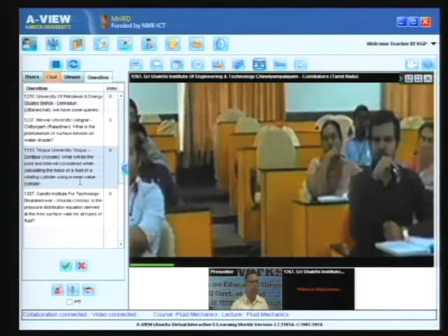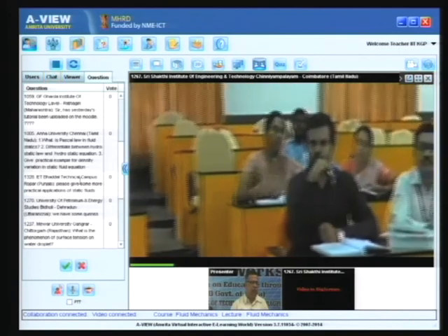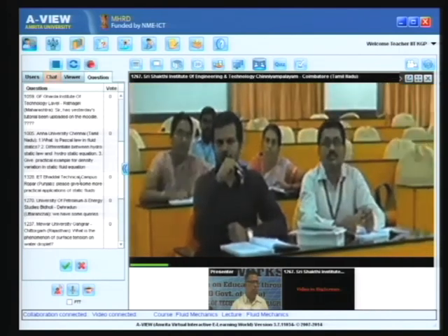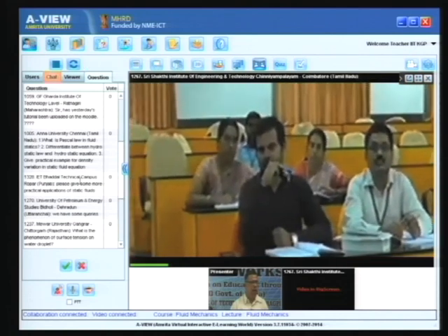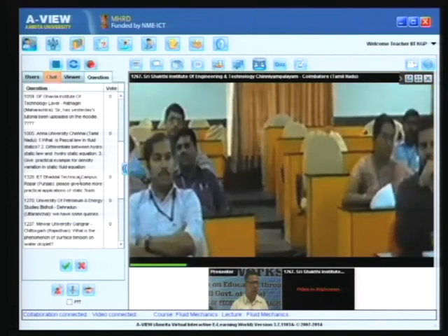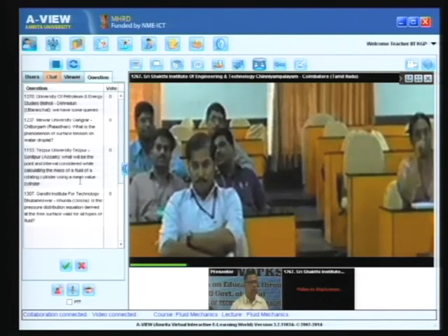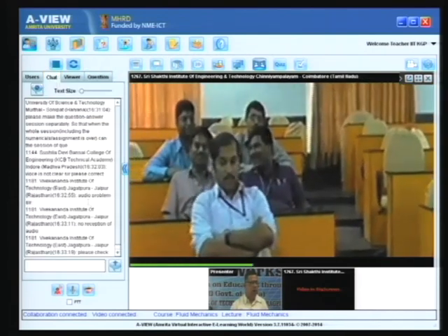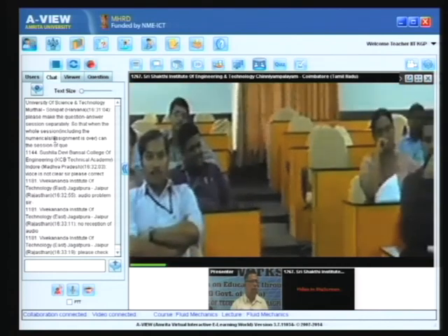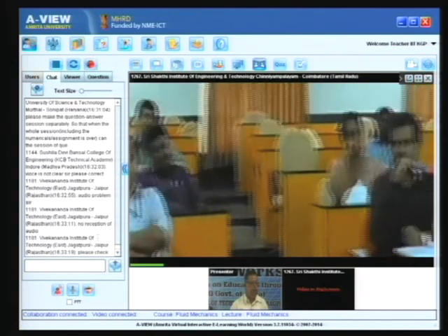You find the pressure distribution in each fluid separately, because in each fluid you have a constant density. So, you will have one constant C1 in one fluid and another constant C2 in the second fluid. Now, you look at the interface at the top liquid, which should be of a lighter density, otherwise it will be unstable. There P is P atmosphere, as we have done.